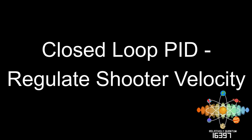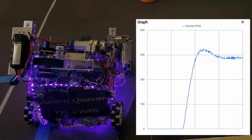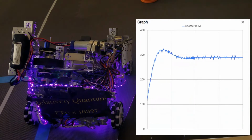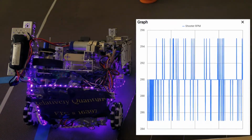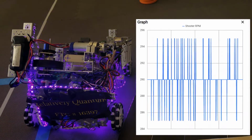Additionally, on our shooter, we use a similar system, but this time, it's not used to hold the position of the shooter wheel, but rather to track the speed it's rotating at based on the number of encoder ticks we read per second. Based on this, we either increase or decrease the power to get to the shooting velocity we desire.